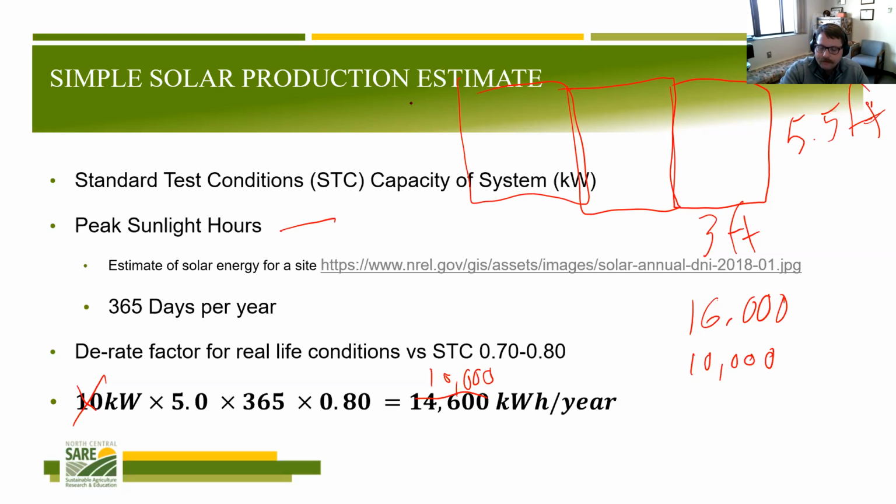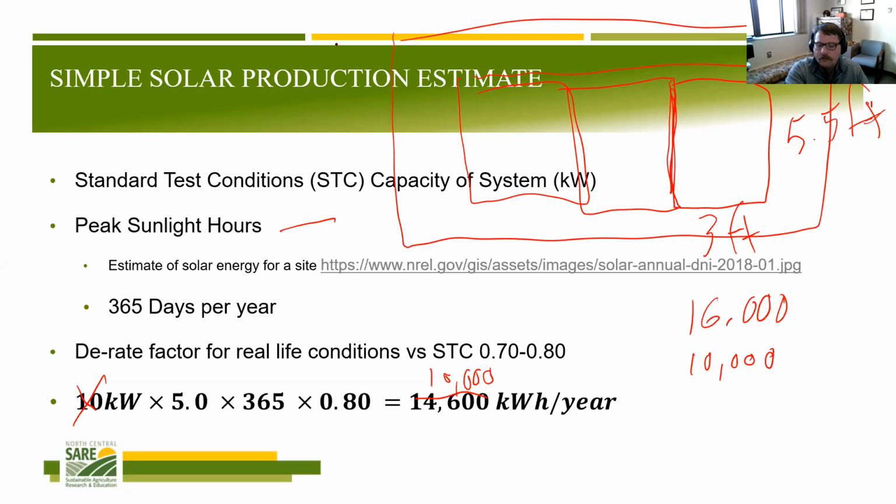Yeah, and there's only about a quarter inch in between solar panels. A lot of times when you have rows, you've got 1 inch between rows. And if it's a roof, you want at least a foot, probably 18 inches all the way around of roof space. So that gives you a little bit of a sense that I have to have a little bit of space around the outside to meet the electric code. So those are some of the considerations.